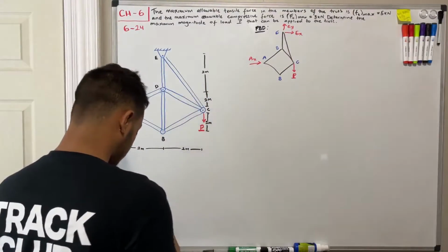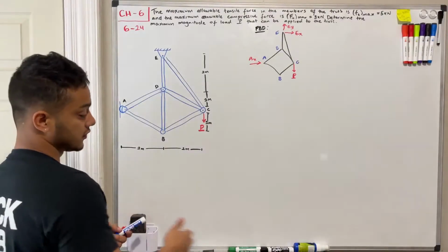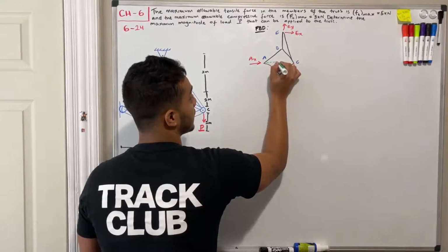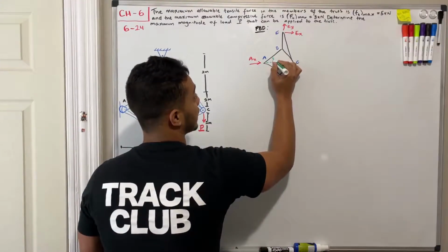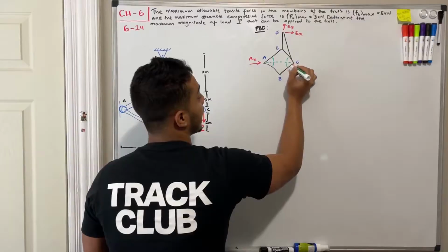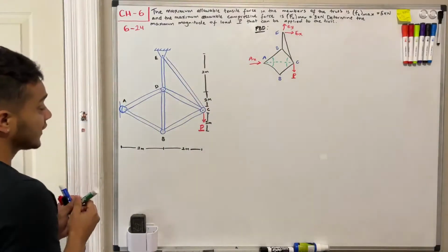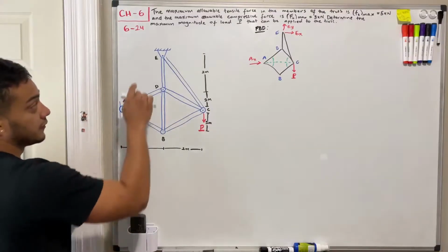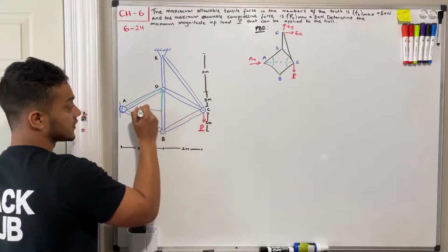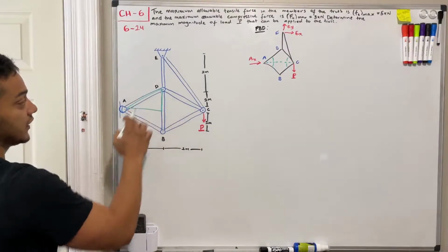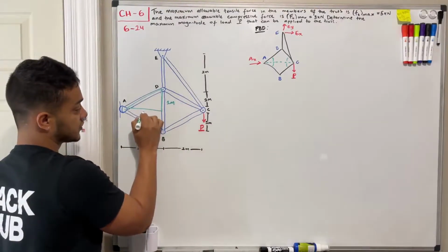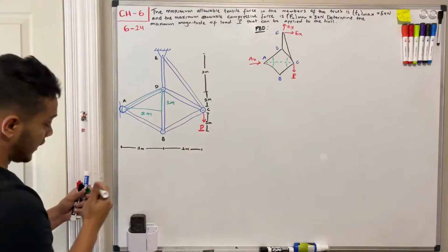Okay. The only thing that we're missing in here is the direction angles, okay? So I need to say, hey, what's the direction of my force, our member? For example, AD, AB, or CD and CB. Now, if we pay attention over here in our big diagram, we can make a triangle like this in order to represent our member AD. Now, it's 1 meter going up and 2 meters going to my right.